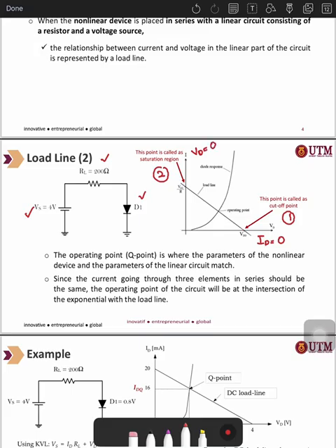After that, how we solve the diode circuit by using the load line is that you need to apply mathematics. You need to apply the KVL for this particular question. To draw the load line, we also apply the mathematical approach, because we want to know the original equation of this circuit. When it is connected in the circuit, of course we know that VS is equal to VR plus VD.